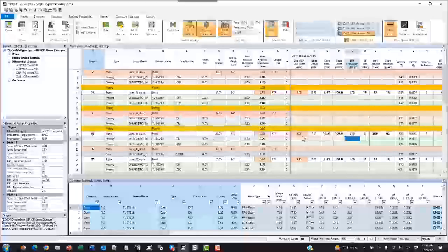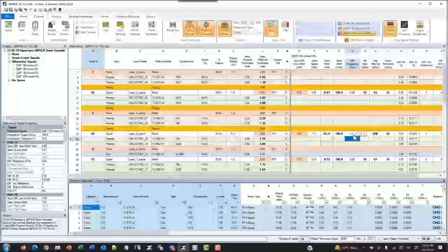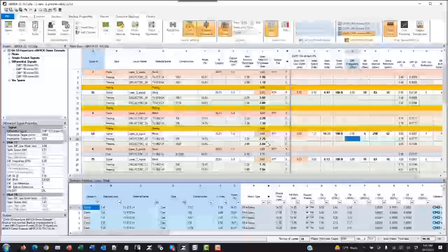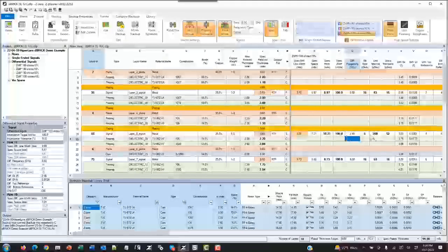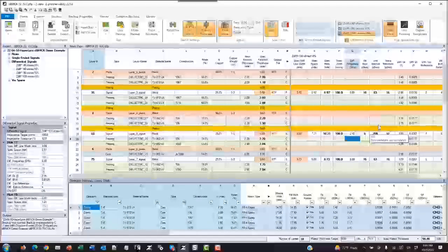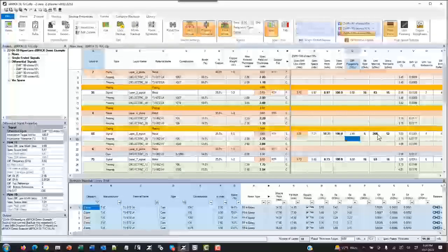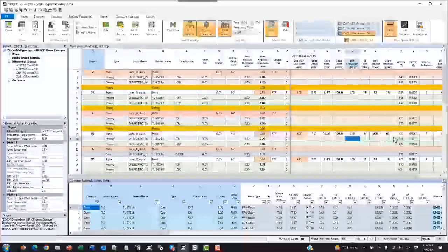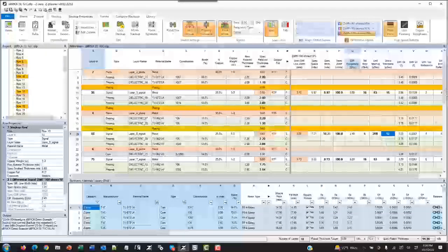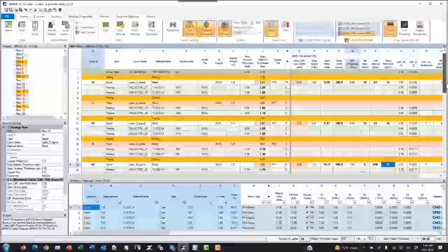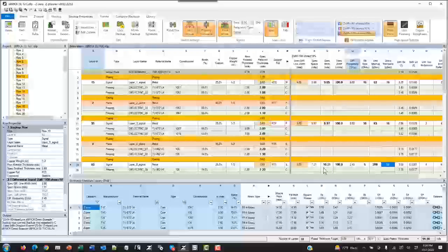If you go down to one of the other layers, like layer 5, you can see it's at a lower frequency, 2.4 gigahertz in this case, and higher loss material is being used. There's the higher DF values, and there's the unit interval, much wider unit interval, 208 picoseconds, and then a 52 picosecond, 25% skew tolerance. That's it. I know that was quick, but hopefully it made sense. That's going to do it for the main part of the webinar.